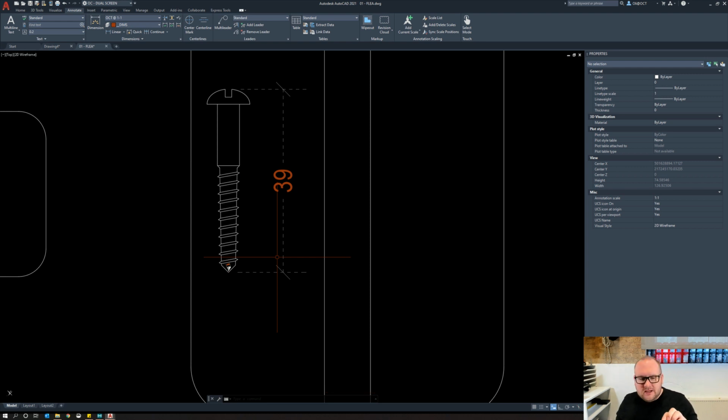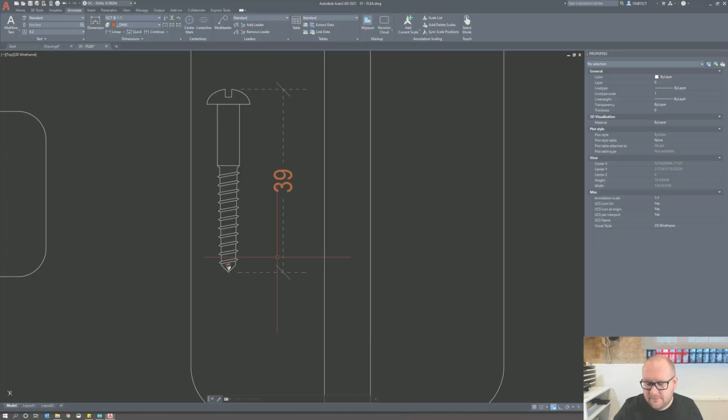Now that it's just tweaking those details, and the biggest thing you'll see those on is curves, because curves in CAD land are actually faceted lines that we just can't see, and they're more organic to our eye. But when the computer's got a lot to think about, it will facet them to save memory. Something to consider. Don't forget regen. It's a very underrated command.